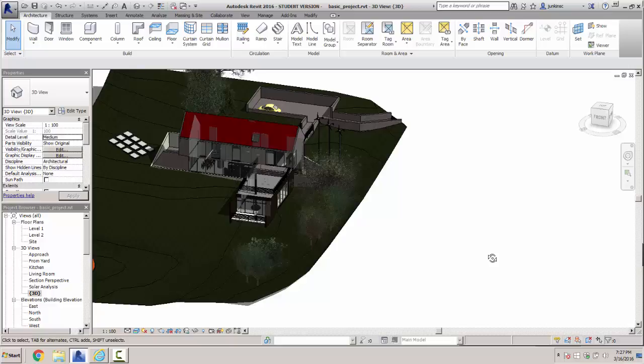And Revit always backs things up. When you open up the next Revit model, it's actually going to create a backup of the old model so you don't lose anything. So number one, make sure your Revit is working properly. Bring up these template files, and again, I've placed them in the Blackboard site. They should be where you found this video, and download them to your desktop in a folder where you'll recognize them. Call them my Revit textbook files, and we're going to use these as bases for starting some of our new projects in the textbook.